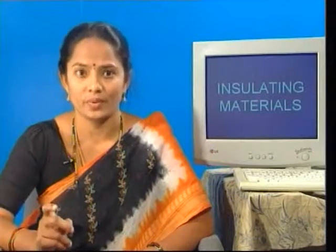The next mechanical property is solubility. Certain insulating materials like varnish should be applied only after they are dissolved in proper solvents like acetone. In such cases, insulating materials should be soluble in certain suitable solvents, but they should not be soluble in water. Otherwise, the moisture of atmosphere will be able to remove the applied insulation and cause breakdown.